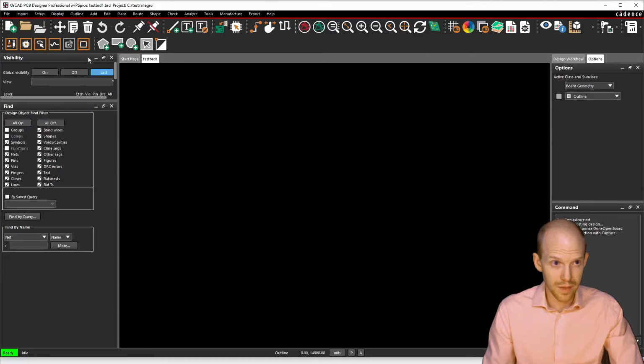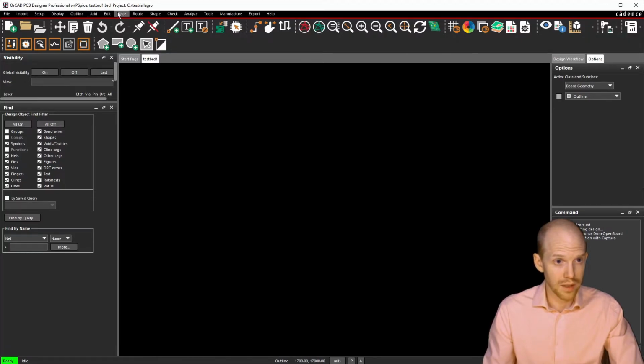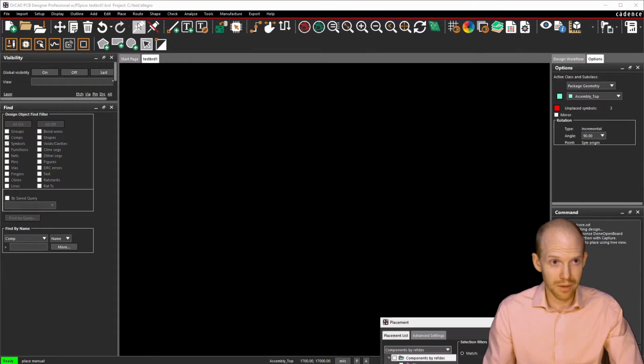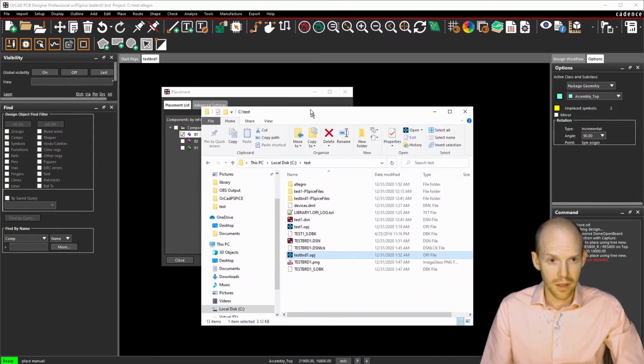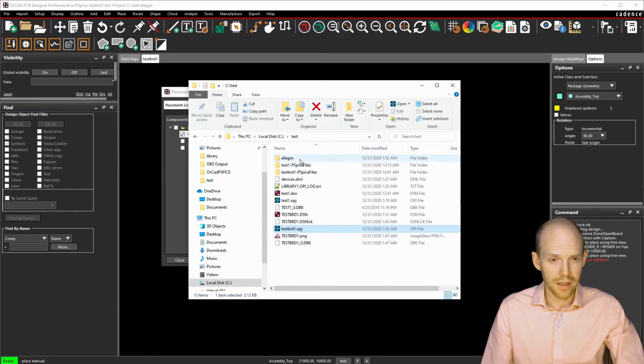That opens up the PCB designer. Now to place the parts, we click Place Components Manually. And you'll see here are the 3 parts that we just made. But you'll notice this R1, we can place that. So you click the checkbox and then you just click again to place it. But the 2 bananas are not showing up. So to get them to show up, we have to pull up our project file, and they aren't in the built-in directory. They were custom ones that I made.